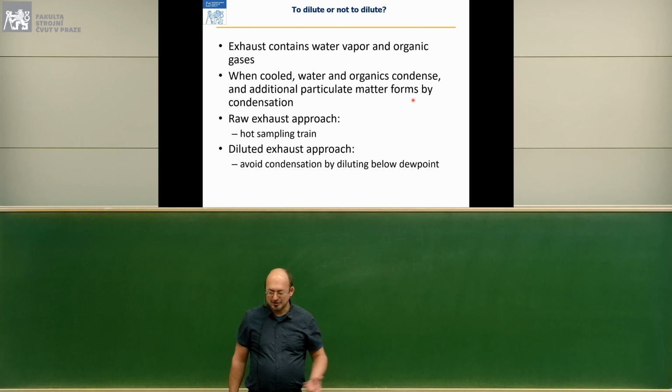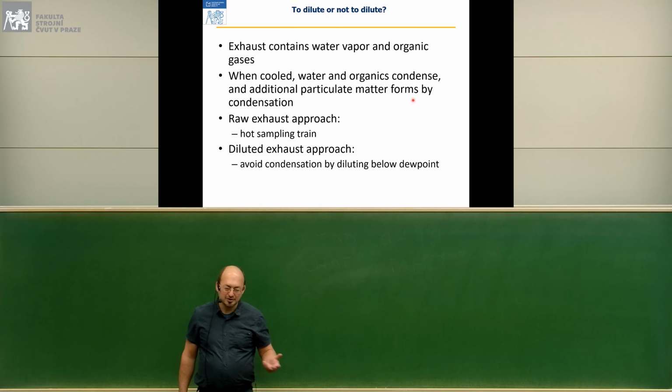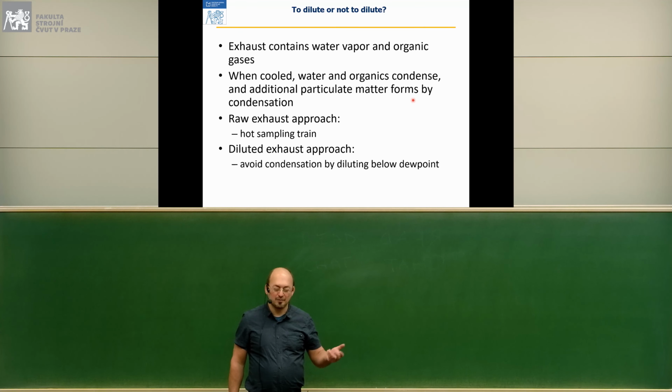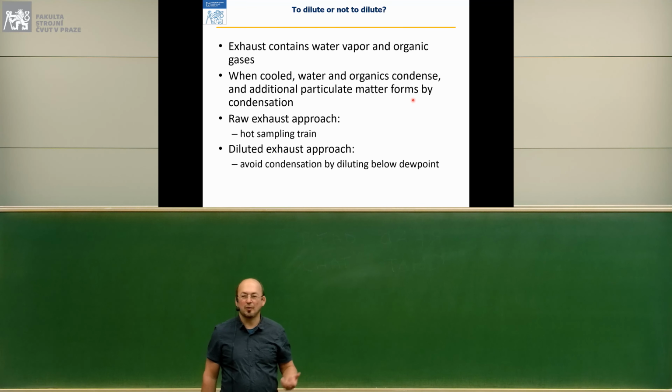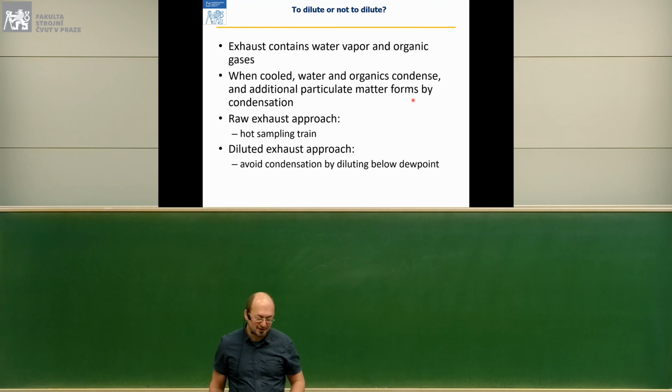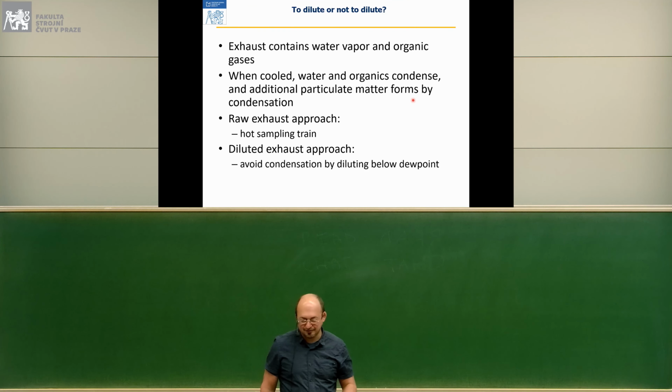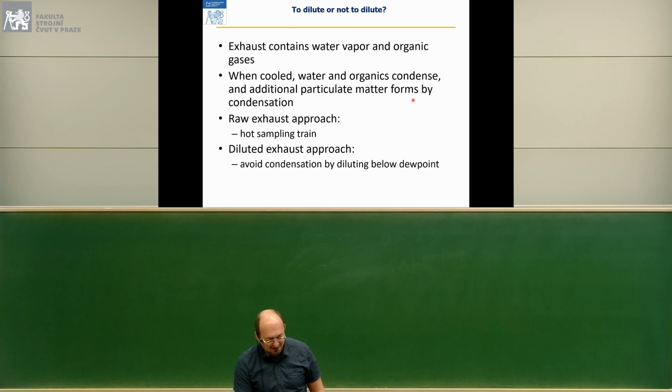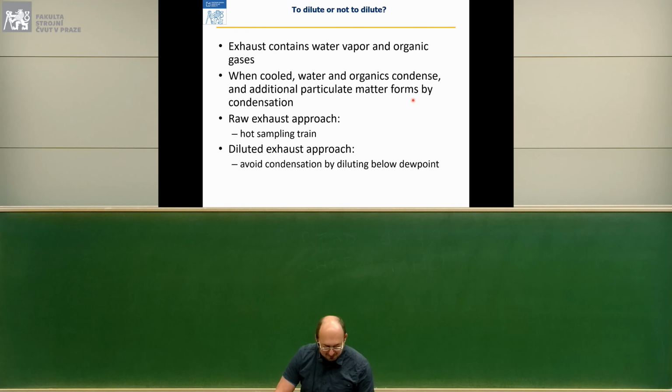And that's not necessarily smoke. Most likely that's the condensed combustion water, especially on gasoline engines. You don't see that much with diesels because they have less water in the exhaust.